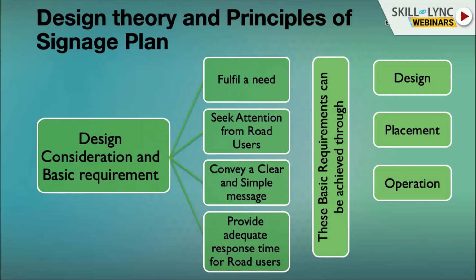For example, if we post a speed of 60 kilometers per hour on a stretch and the traffic has increased, so the speed has come down because of the increased volume on the road, the 60 kilometer per hour speed limit post has to be replaced using maybe 40. And how do we do that? We do that through an analysis like speed delay surveys or CCTV cameras or using interceptive radars to assess the speed of the vehicles traveling on it.